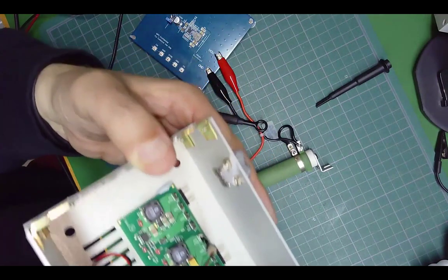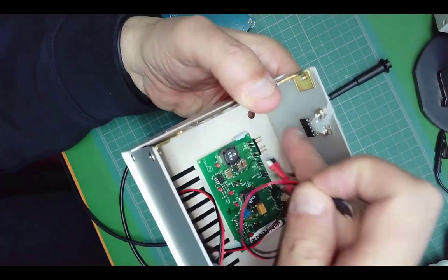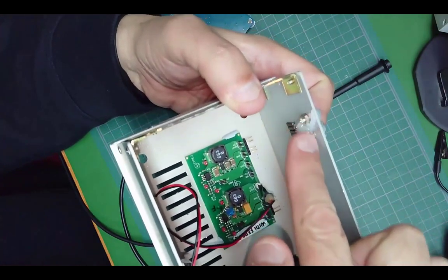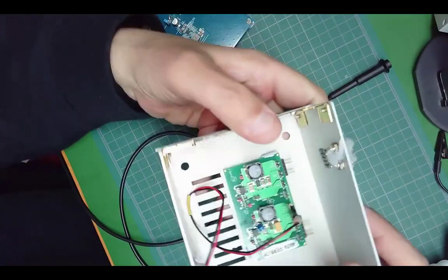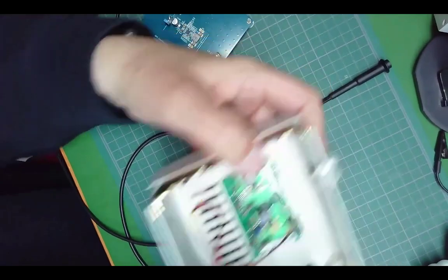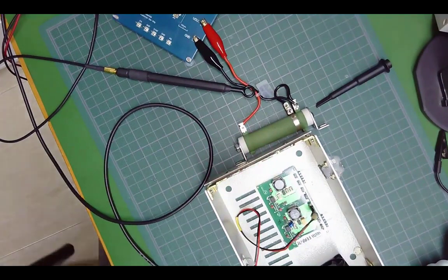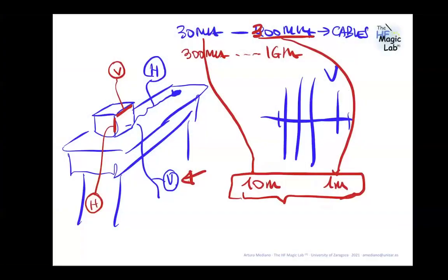With some kind of cable, I can power my board from here instead of going through the enclosure. Then I have two capacitors of some picofarads, connected at 360 degrees to the metal enclosure. This is a very nice way to filter high frequencies, hundreds of megahertz. I did not have time to do this demo, but the effect is very similar to the ferrite effect. Okay, thank you.